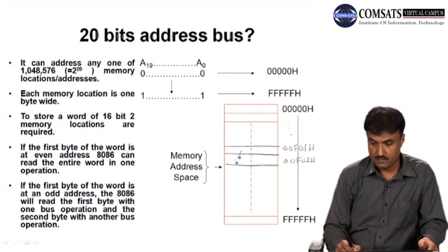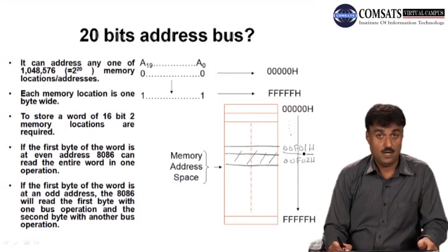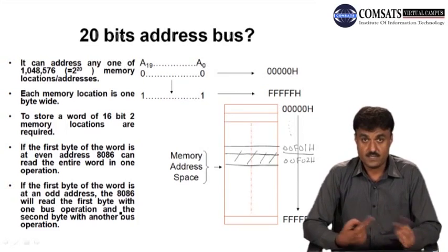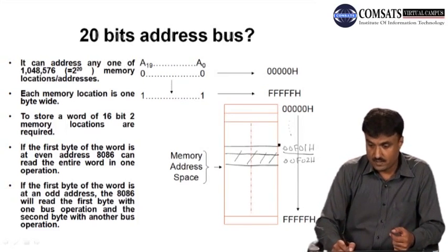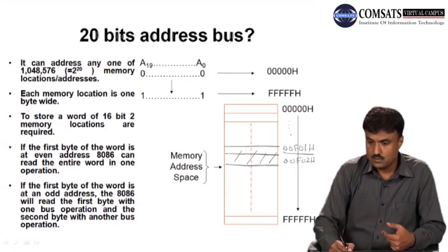If you store somewhere here, for example, this is the starting address. This case differs in little endian and big endian, we will discuss that, but here suppose this is the starting address of the 16-bit word data which we stored in 2 locations. So if we want to access that one, we will access it by using the first address.